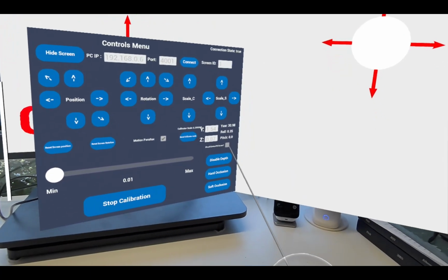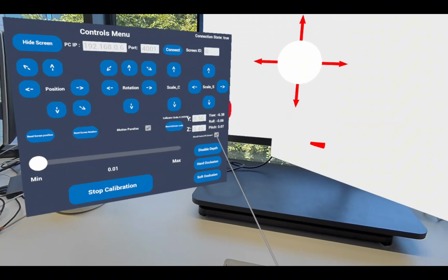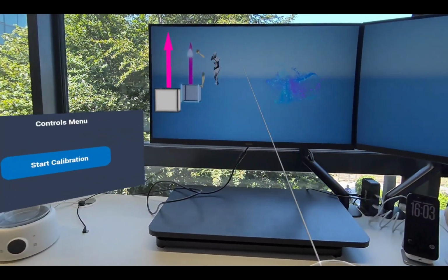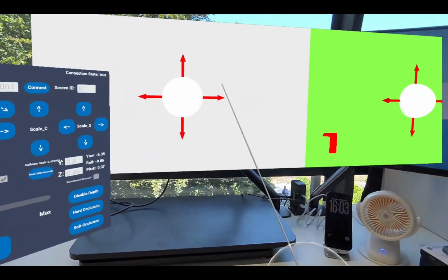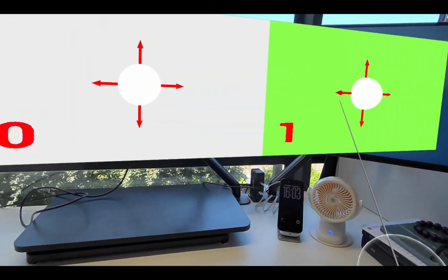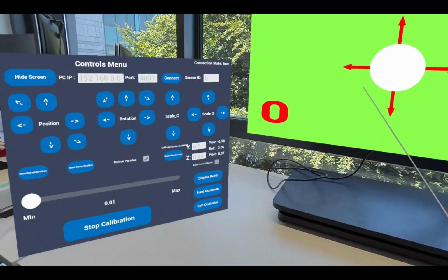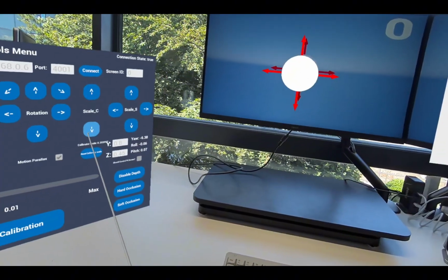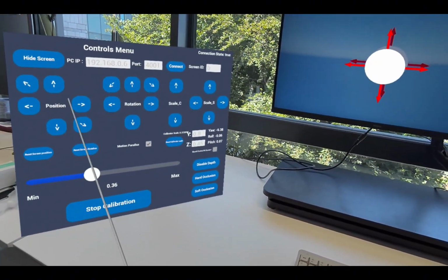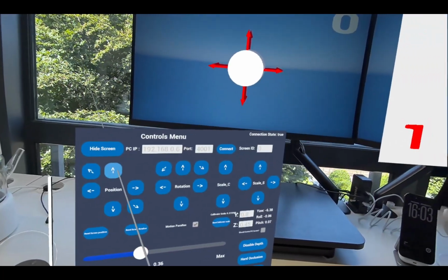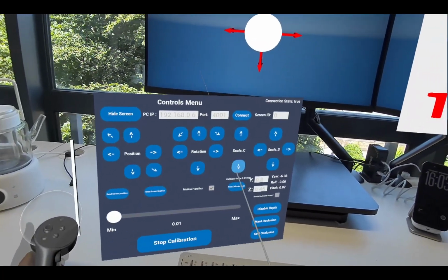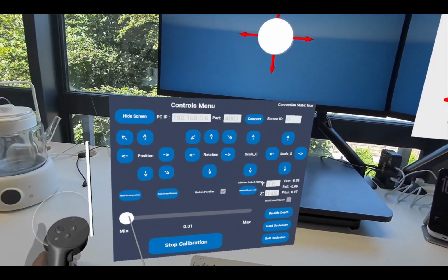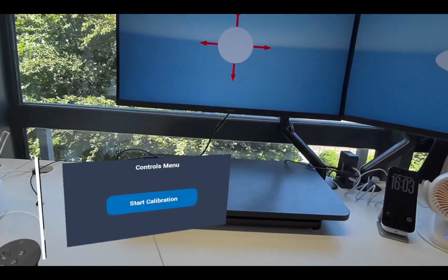Disable Should Control PC Screen for this screen. When this option is disabled, the screen will use the corresponding position defined in the PC nDisplay configuration after calibration. In this example, the two screens will therefore be arranged horizontally according to the nDisplay preset. We can now precisely adjust the size and pose of the calibrator until it aligns with its counterpart displayed by the PC. Because the HMD screen is currently controlled by the screen settings in the PC nDisplay configuration, we only need to calibrate the calibrator itself. The predefined screen size will be applied automatically when calibration is completed.